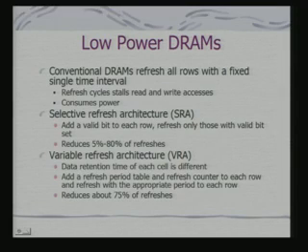Then we have DRAMs, because DRAMs are primarily used for implementation of main memory blocks. Conventional DRAMs refresh all rows with a fixed single time interval. That is the typical DRAM refresh cycle. Given a DRAM, it has to execute refresh cycles at regular intervals, because the data is stored in capacitances, the charge is stored in capacitances. So, the charge will decay off. So, I need to refresh so that I can retain the charge.